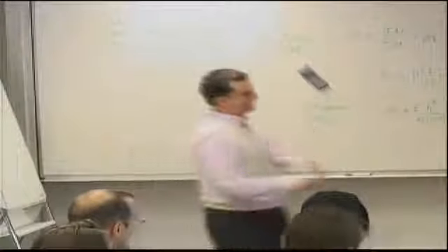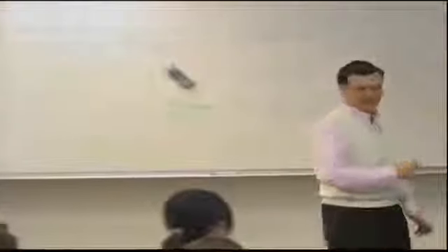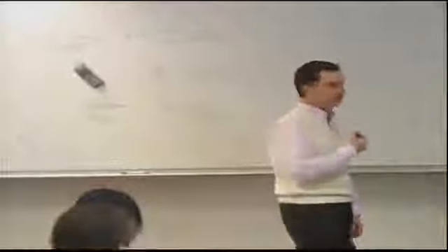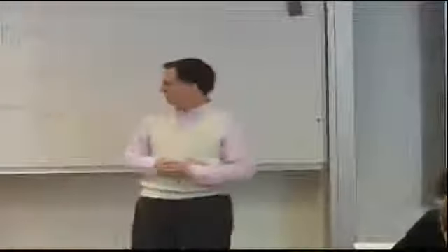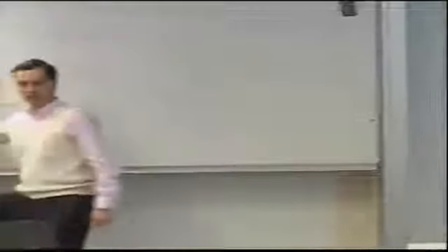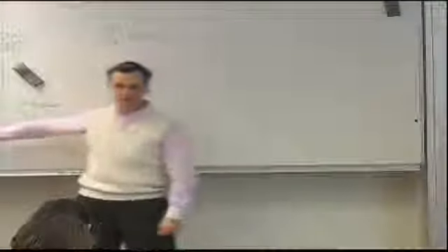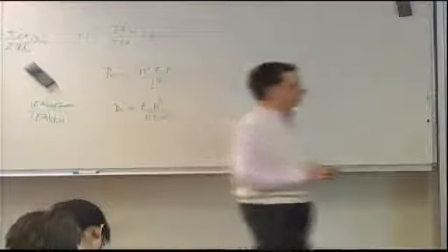Notice the x-axis here is B over T. The x-axis there is the fastener spacing S. So as a function of S, once you have crippling, it's a constant value, even though the crippling load changes with B over T. But B over T is unrelated to S, the spacing of the fasteners.